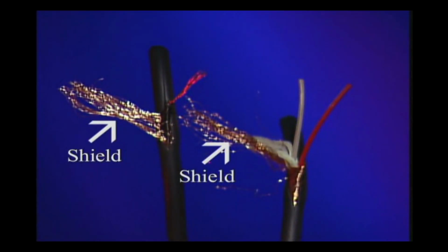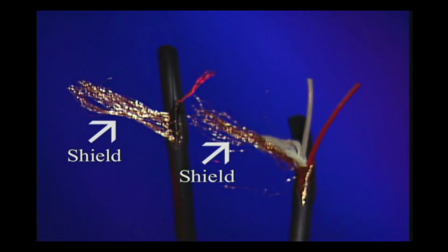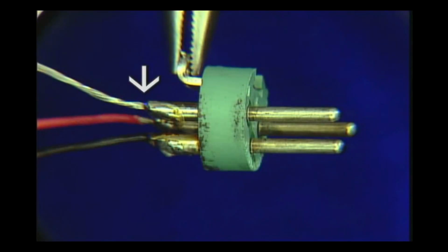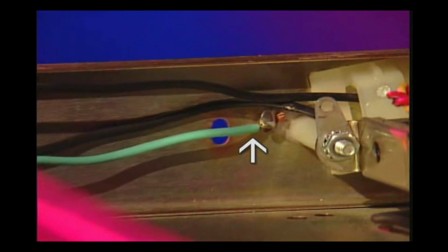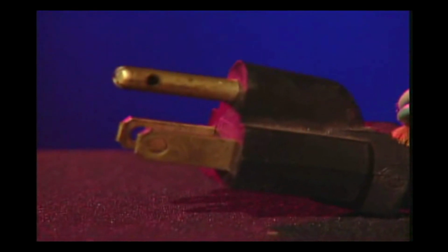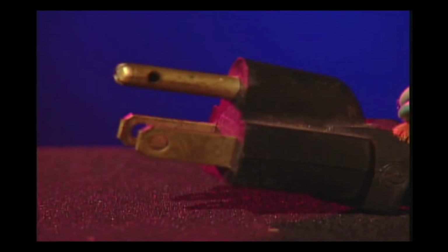In every cable, connector, and electrical device used in an audio system, there's a grounding capability. In a cable, it's the shield. In a connector, it's the sleeve or a pin. In a device, it's the chassis ground. The purpose here is to maintain the flow of ground throughout the system until it can safely be carried, ultimately, to Earth through the 3rd prong of a 3-prong AC plug.